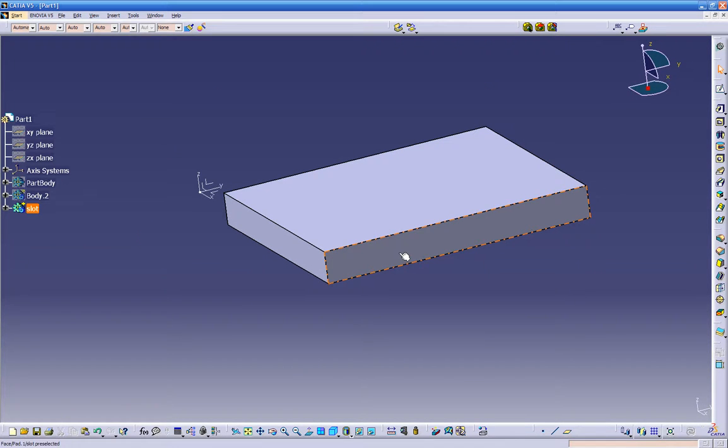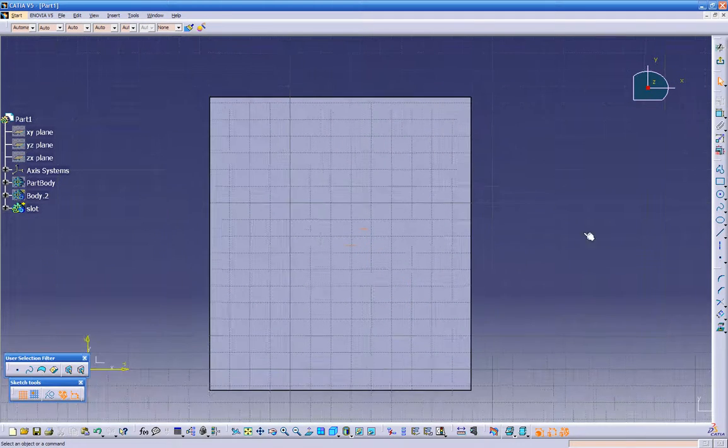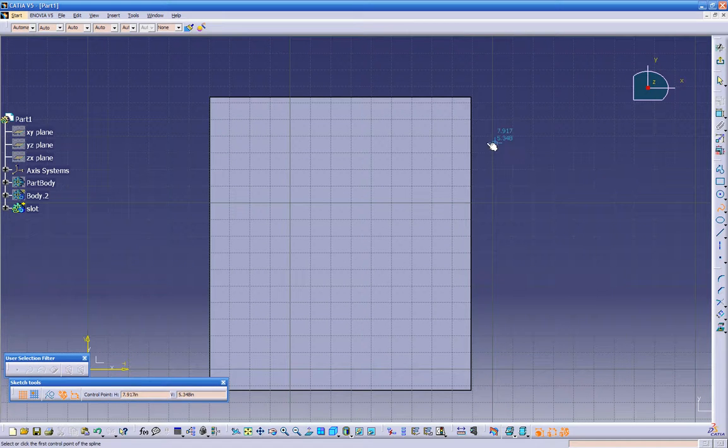Now let's create another sketch with the profile of the groove, which is going to go through the surface. So we can pre-select the surface to open a sketch on top of it. We don't have to go down here. We just click on the top of the pad, open a sketch, and we can create ourselves a groove. So we can click on the spline. That's gonna go to our part. Click escape.